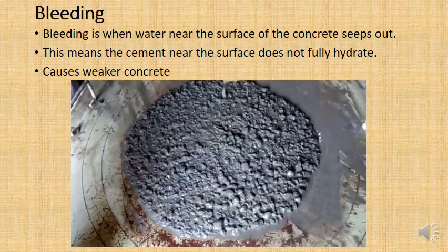So what you see down here is actually a slump test, and it's a collapsed slump. That's segregation. You can see a pile of rocks, aggregate particles in the middle, and all around the edge you can see a big grey puddle of cement water. That's going to be a very weak concrete. When the water is bleeding out of the concrete like that, it leads to a weak concrete, because you're going to end up with it not being consistent.